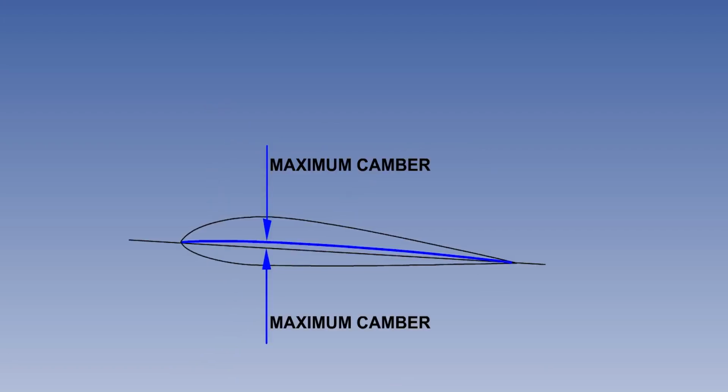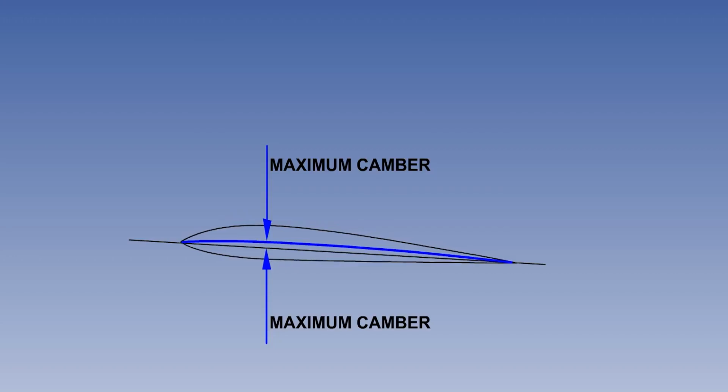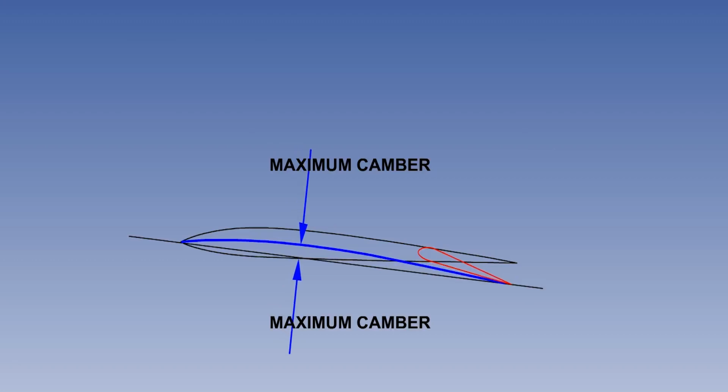With the low Vs comes the penalty of a low efficient cruise speed, because of the excessive drag generated. It is thus better to use an aerofoil that is efficient at a high cruise speed, with the ability to increase camber temporarily when it is necessary to fly slowly, such as on the approach. This can be achieved by the use of hinge sections of the wing trailing and leading edges, collectively known as flaps.